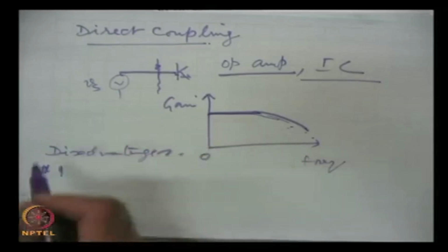So, we can design the amplifiers more accurately individually, and then use RC coupling, because for DC purposes the capacitors keep them isolated. The biasing and the Q points, the operating points, are not affected. But when we use direct coupling, we are connecting them for DC voltages also, and hence the design has to be done more carefully. We will take a design example to illustrate what I have just said.